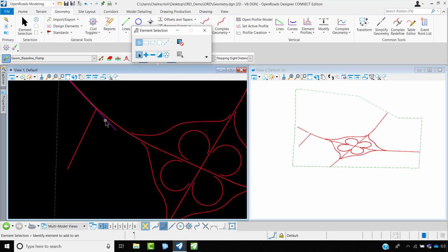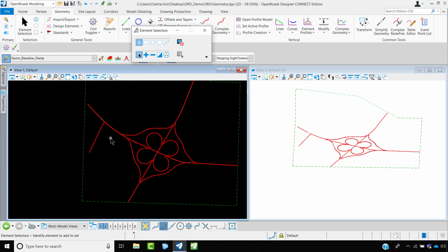So in this way, you could make the changes as per the standards by reviewing it through the Civil Message Center, by knowing what all are the standards which are being violated, and make changes with respect to the codes. Or else, if as per the site condition you have to deviate with respect to the standards, you could keep the same values.